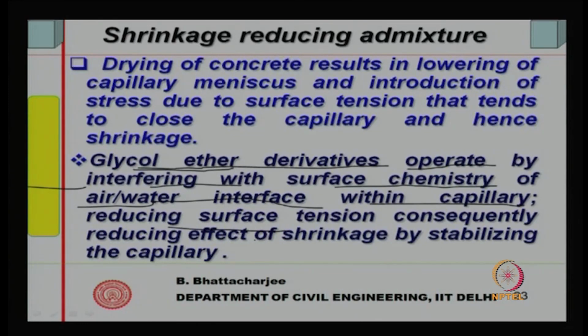Well, if you look at it, an air entraining agent also reduces the surface tension, but it has got a head and tail, one of them being hydrophobic, another being hydrophilic. The hydrophobic side actually traps the air bubble, but here this will not happen.